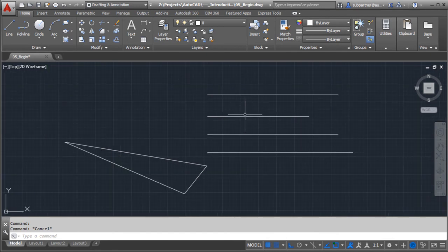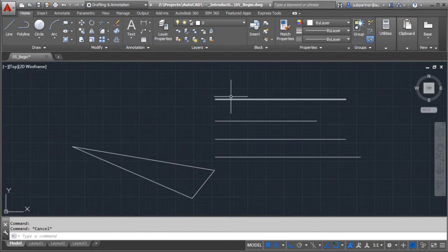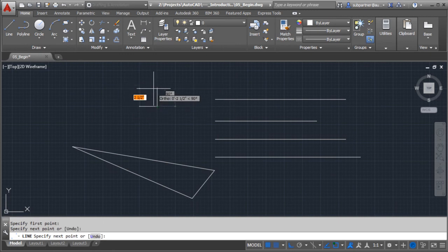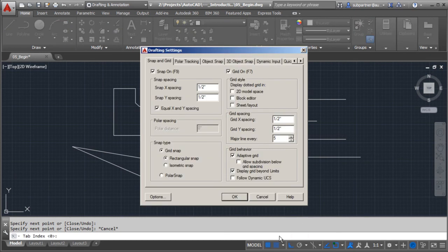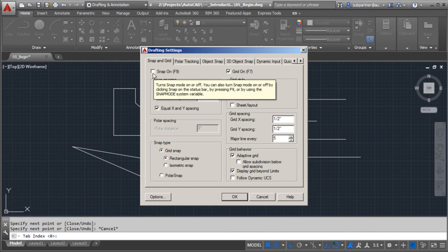So you'll also notice some of the behavior that's associated with when I'm drawing lines. If I'm drawing a line here, we'll go back to our line button there. You'll notice I'm kind of snapping here. Well, I can control that snap. Right now, it's basically snapping to points so I can get a certain kind of precision here. So instead of infinite points, it basically snaps at certain intervals. If I wanted to change that, I can come over here to our snap settings, and we could turn the snap on or off simply by going here, or you'll notice we can just hit F9.